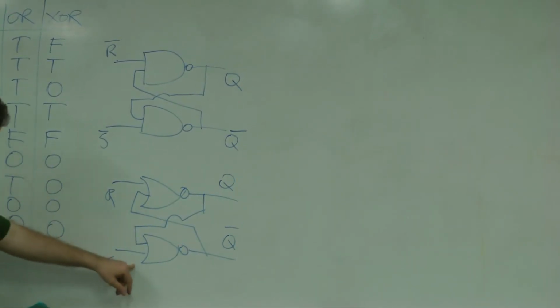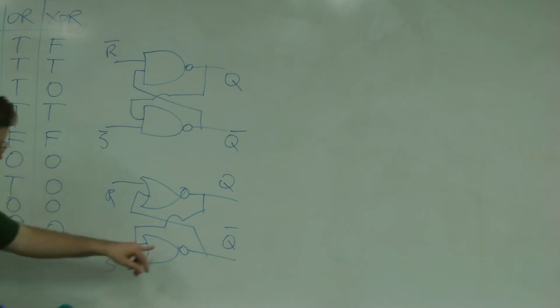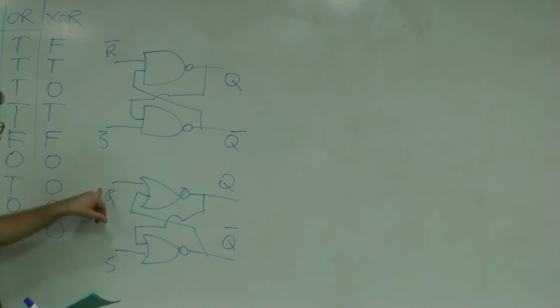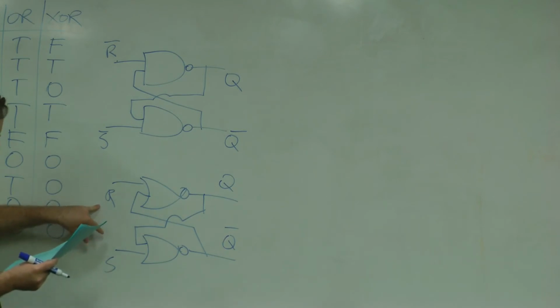So if we wanted to set this to a value of 1, we would send S to high and R to low.